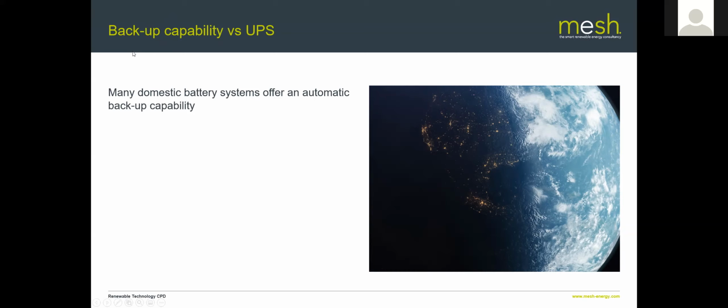There will be a small break in service as the contactor opens and the battery resumes operation. It'll probably be only a second or so. You're not talking about huge long periods without power, but it would be enough to, for example, drop a server. So if you're running a data center, you need a UPS, which is a slightly different arrangement electrically. But what we're talking about here is typical domestic situations.